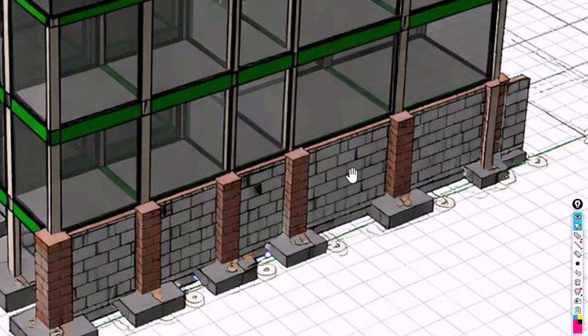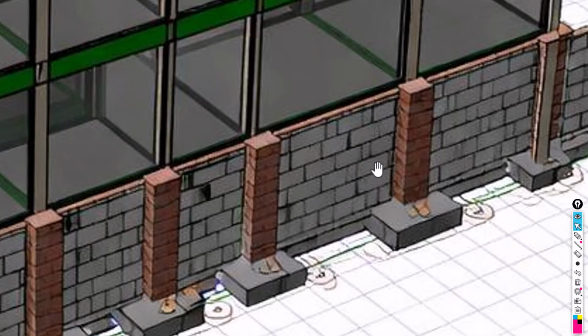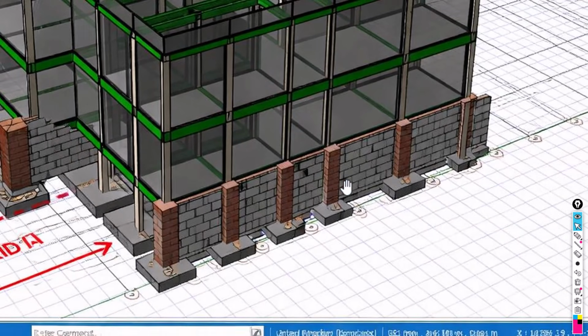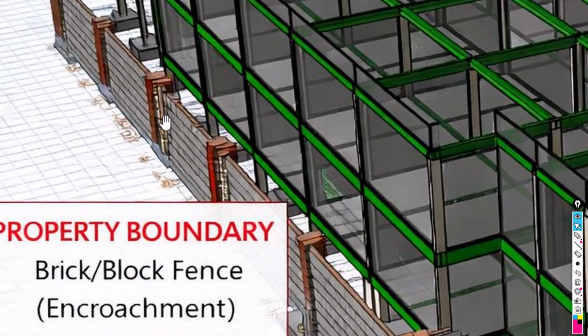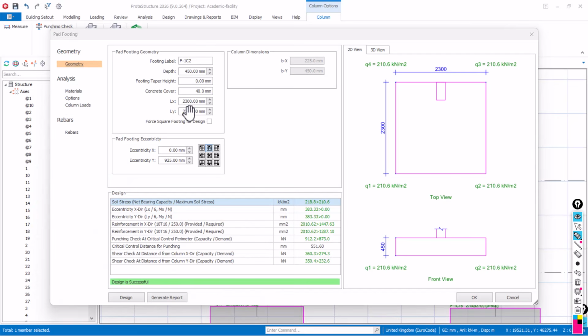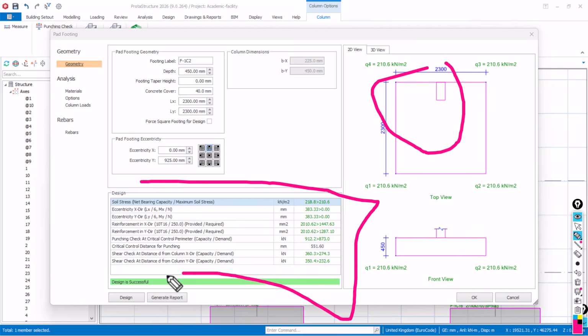So in that case, that gave room for an eccentric column design. But when designing for eccentric columns, there are several problems that people encounter, which I'll show you in this video. But here is the real problem for eccentric footing: even if your software says that everything is okay, the big issue is that due to the uneven, non-uniform soil that is always found at the base of the footing, you will have an uplift or overturning.